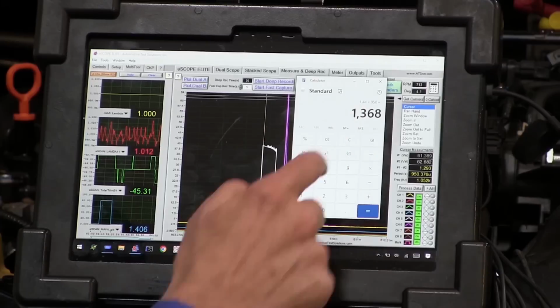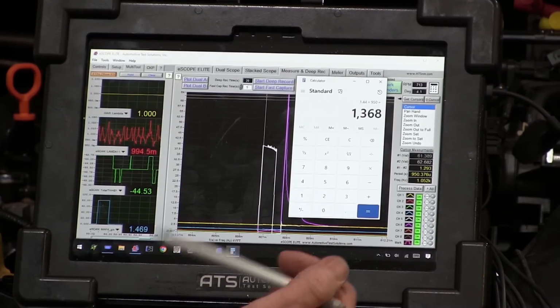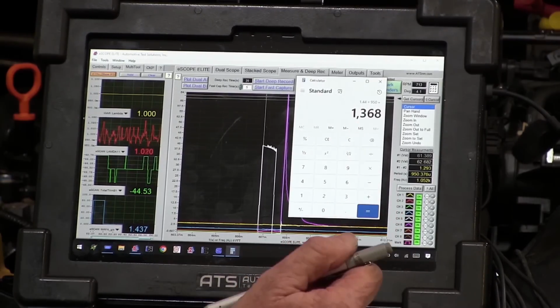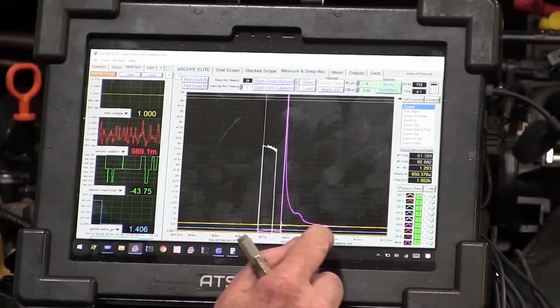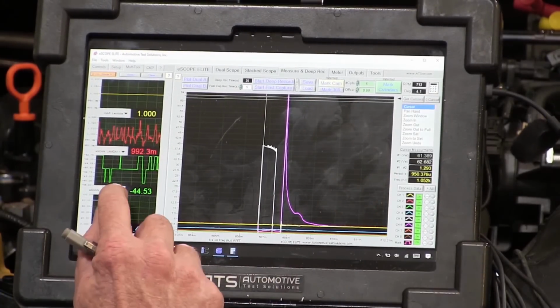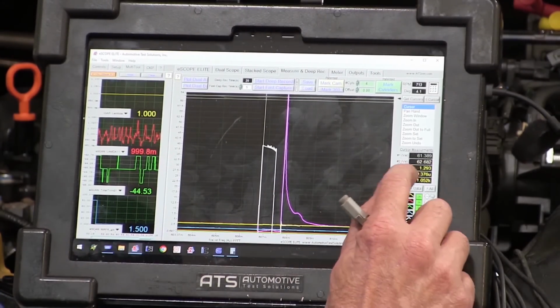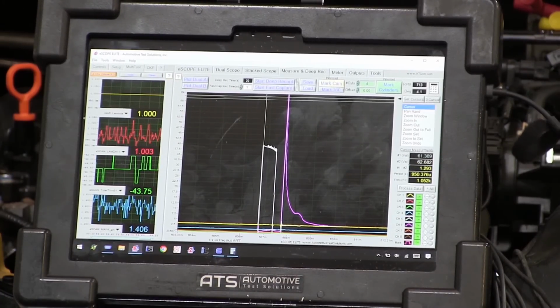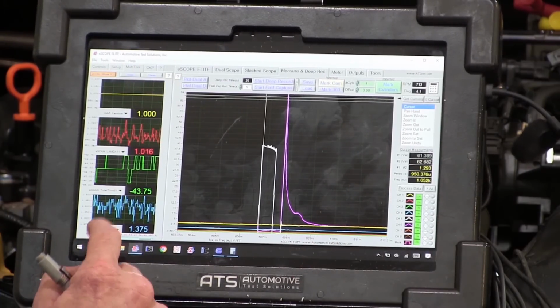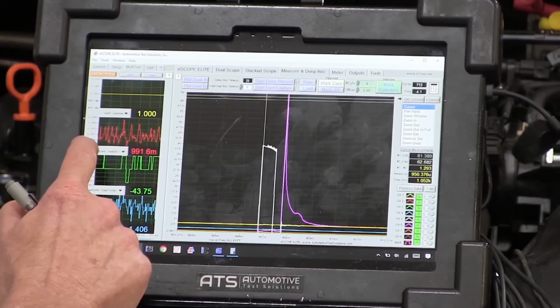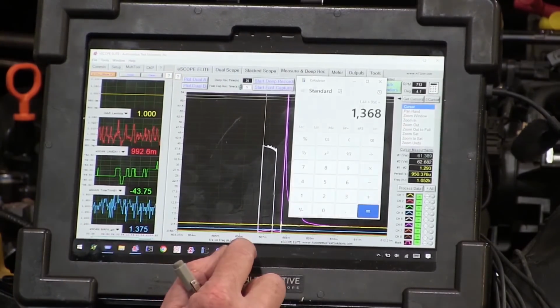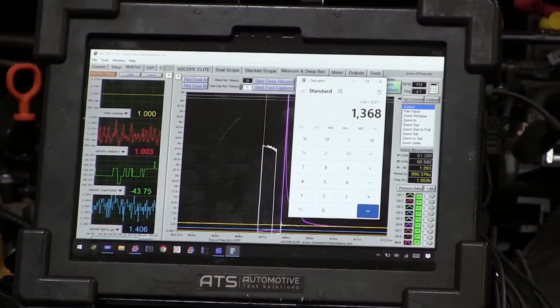But this is way too much calculated on time. That's what the processor figured it was going to be by the base equation. Now, what happens is that's after I take away 44% trim. I'm pretty close to where I think it should be: 900 microseconds, 800 microseconds. But okay, at 900 microseconds we have control, because we've got a lambda of 1 out the tailpipe and by this O2 sensor. But that's only after I'm taking away all that fuel. That's what the base equation is.